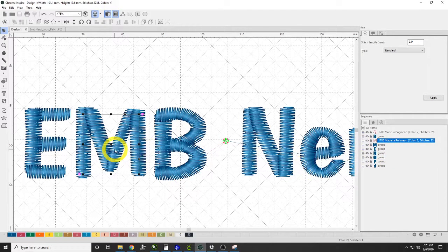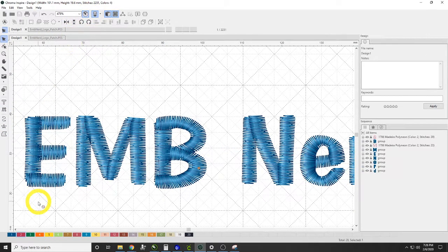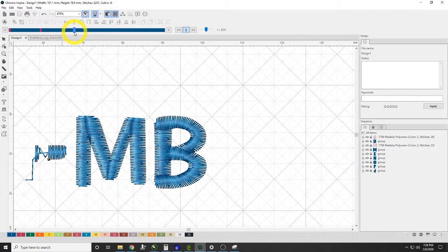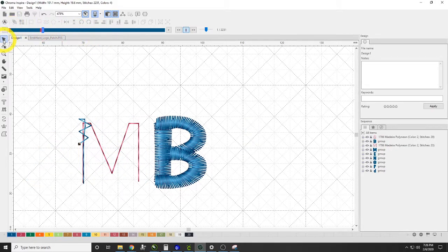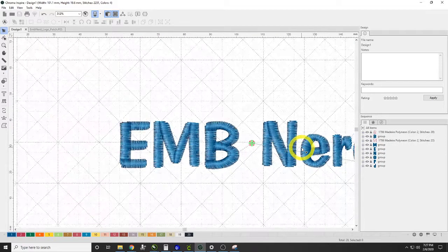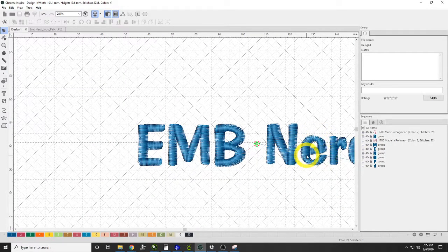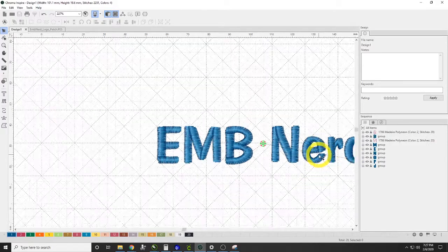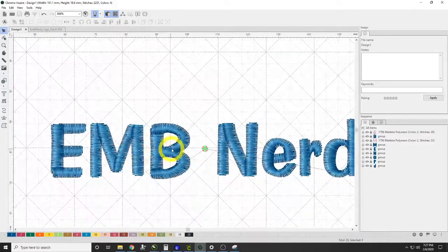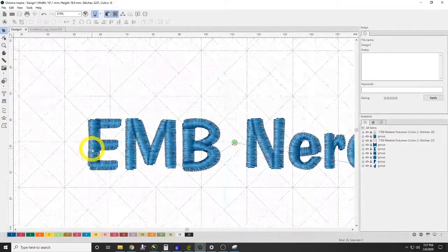And finally, we'll go with the E. We'll jump back. We're going to do the same thing, because if we do the slow redraw, you'll see that the E, let's jump over here to the E, is going to start kind of there on the bottom and go up and around. So let's digitize that as well. I hold down the control key and I scroll out, and when I hold down the control key and scroll, it moves away from my mouse, or if I zoom in, it moves towards my mouse. If I don't, it just moves in and off the center, and I prefer that.